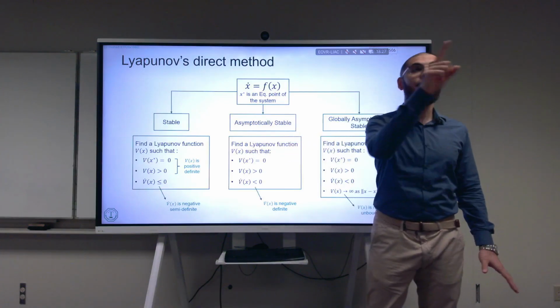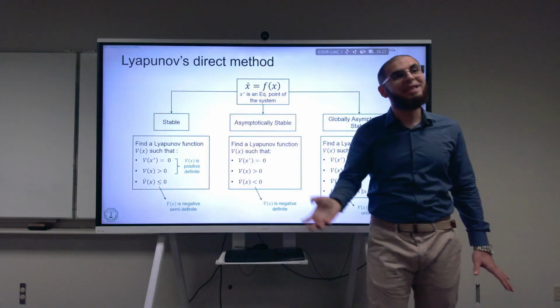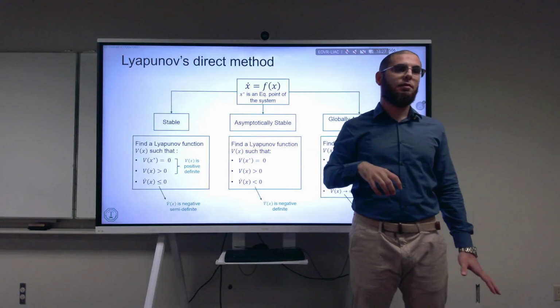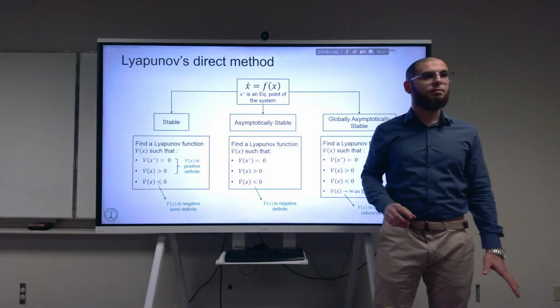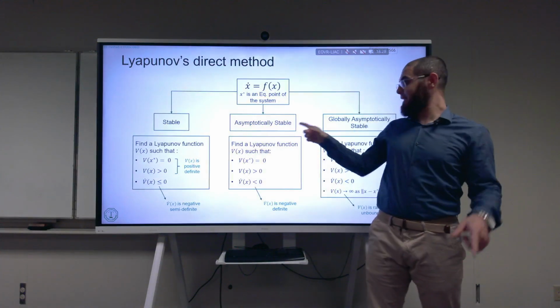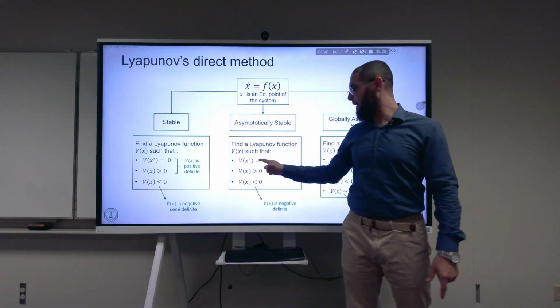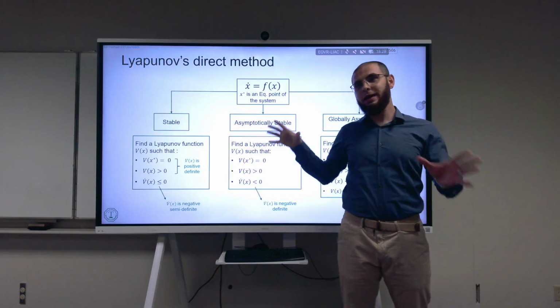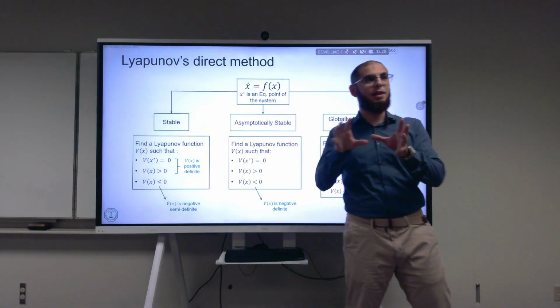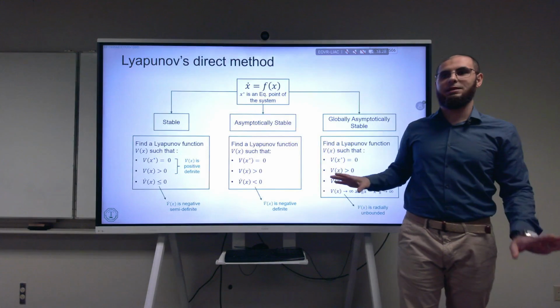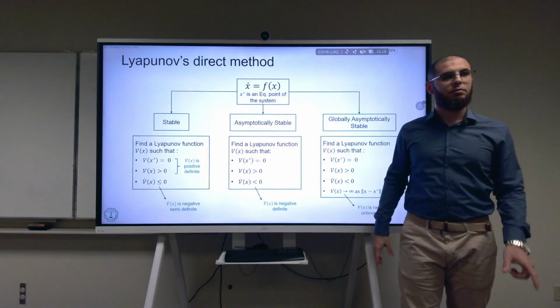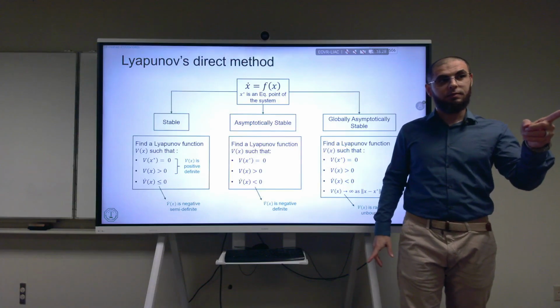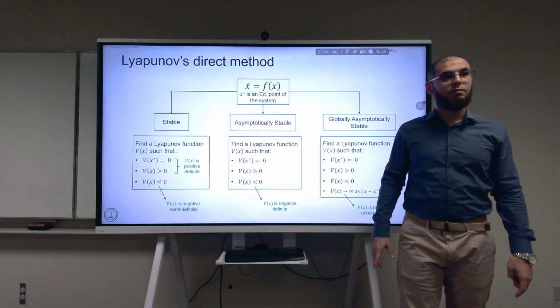So even if you linearize, you're linearizing around the point. That's what I'm saying, that point is going to be the point where we linearize that system. Exactly. And here, the point is already the one you evaluate the Lyapunov function at. So it's always the stability of the equilibrium point. There's no such thing as the stability of the system. If we change that equilibrium point, then it might be stable or unstable for that.